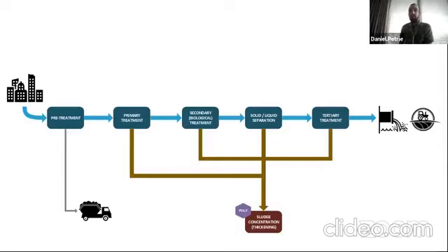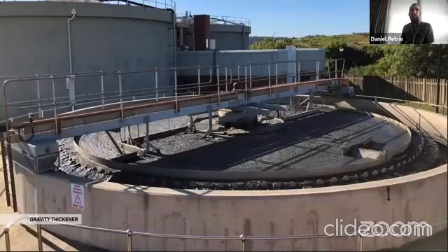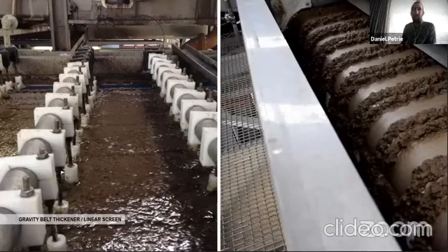And you can do them in combination, or you can use different technologies depending on which sludge stream you want to concentrate. And that thickening process may make use of gravity separation. So again, just letting dense material settle down and letting cleaner water overflow the top. It may use more sophisticated mechanical machinery, like a gravity belt thickener.